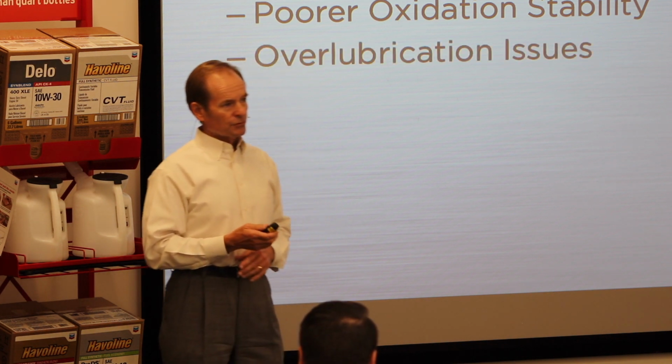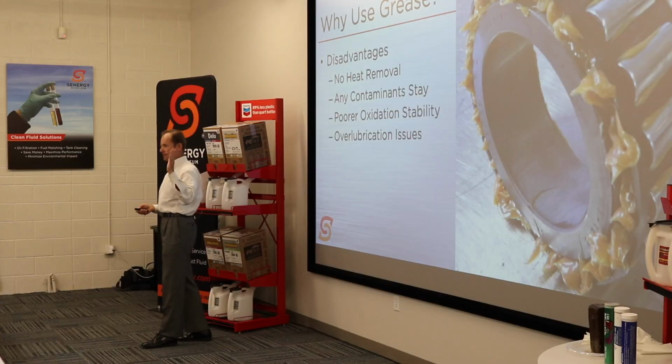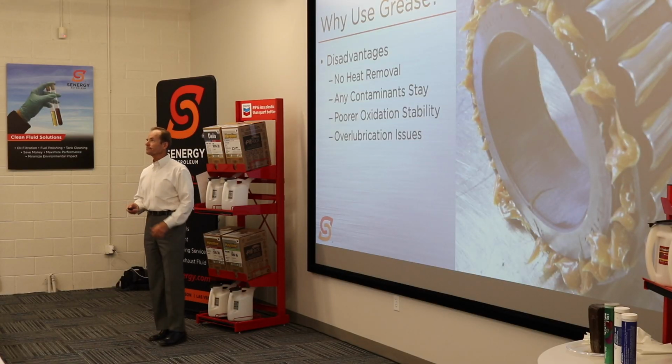And then there are over-lubrication issues. Okay? You're much more likely to run into over-lubrication problems with a grease than you are with an oil. It can be done with oils too, in some cases, but it's really more of an issue with greases. And I have a slide on that later on when we talk about some of the real-world stuff.